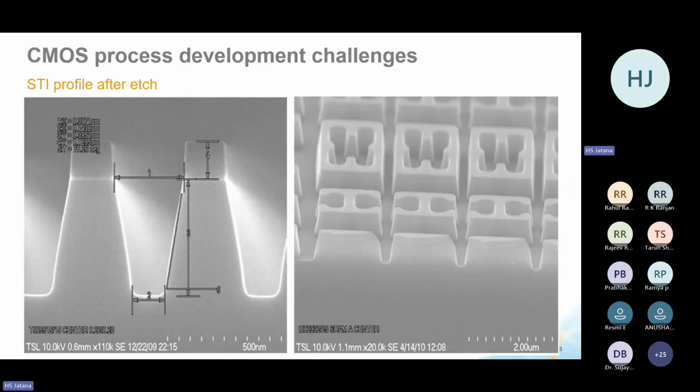So you can see this picture. The first unit process will be etching. So it is doing etching only. You have made a wafer, you have etched it and perfected it so that you are able to make that structure of etching of particular dimensions. So this is the profile after etch. You will only do this particular unit process of etching, nothing else.